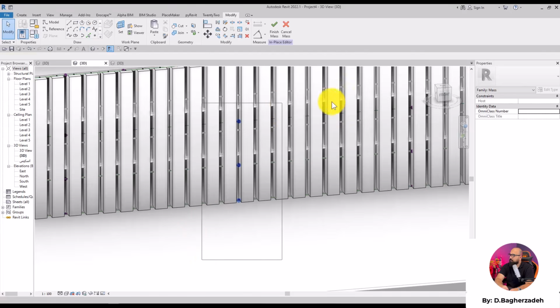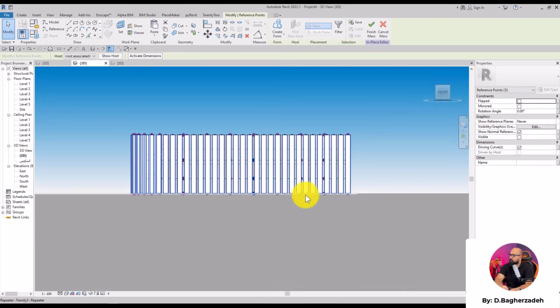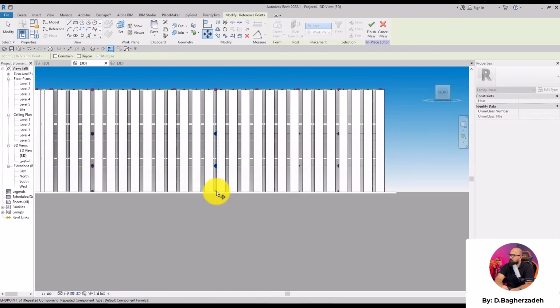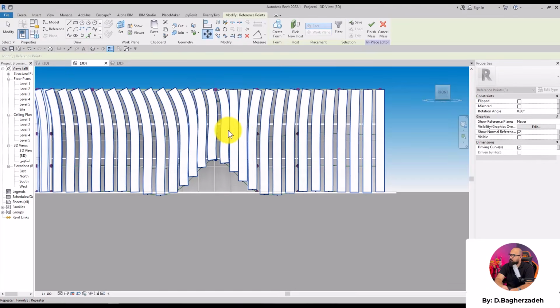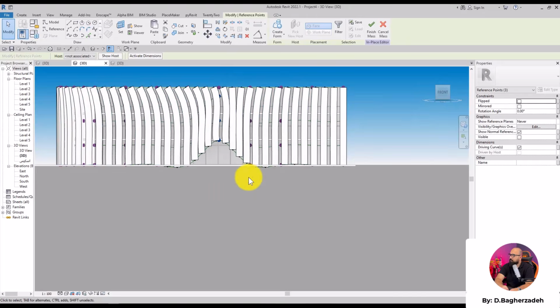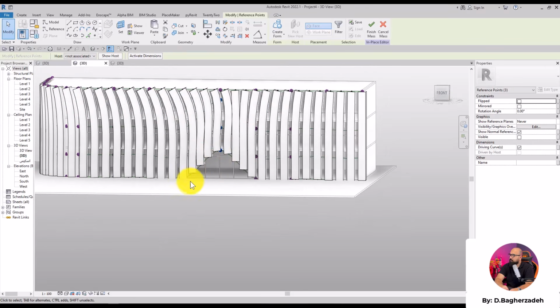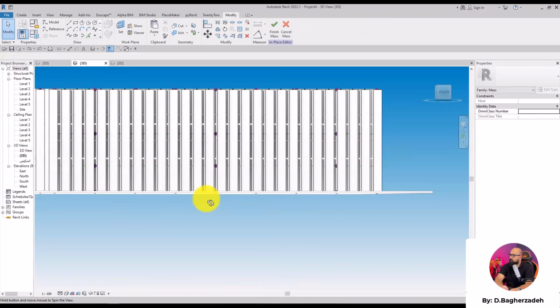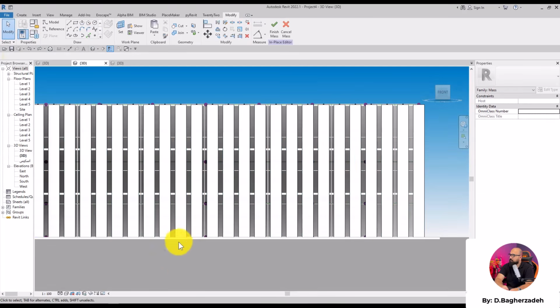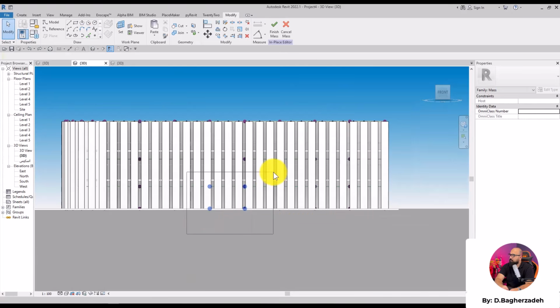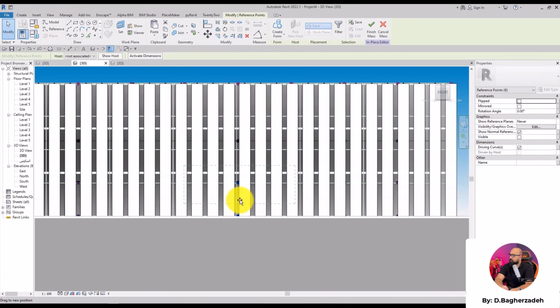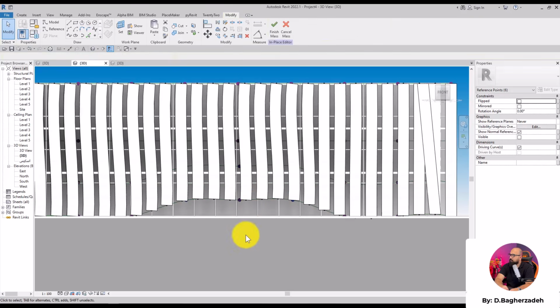Well, let's see. For example, I'm going to go ahead and start moving these vertices around a little bit. Like, for example, let's start by moving these bottom points upwards. Okay, as you can see, we have a bit of deformity on our hands. Well, this happened because first, the size of the profiles is too large, and also, we actually rushed this modification. Now, to prevent this from happening, we actually need a bit more patience, like go ahead, select several points here, and gradually move them upwards, like this.